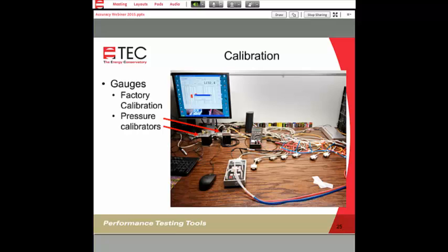We cycle them back and forth to a calibration laboratory to make sure that they are reading properly, and we're checking those against more of a primary standard, to again ensure that you're getting the proper readings. So this is generally what we're doing. We do have a custom piece of software that does all of the calculations, generates pressure, and looks at all of the different values that are taken over the entire range of the gauge.